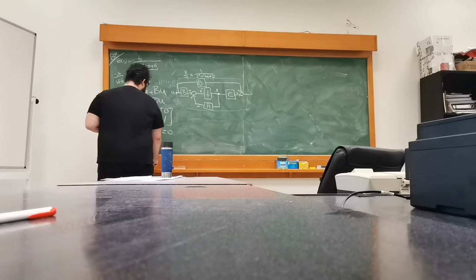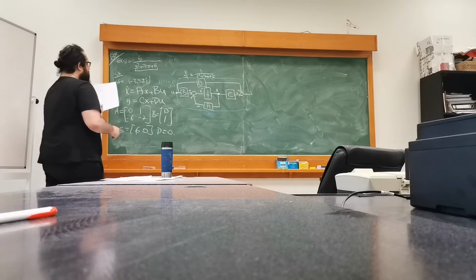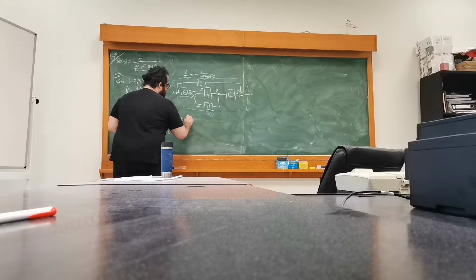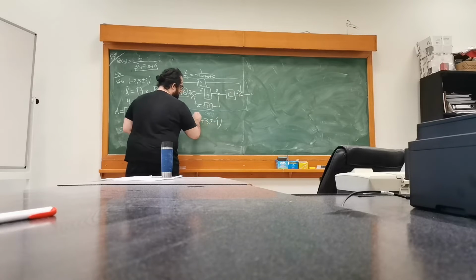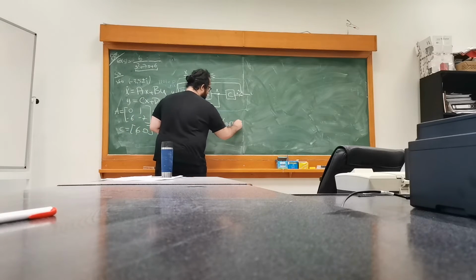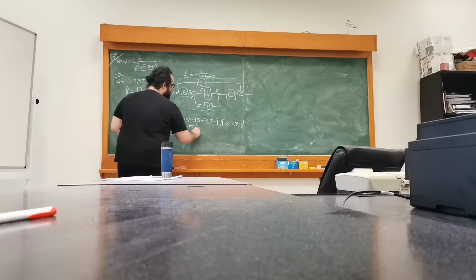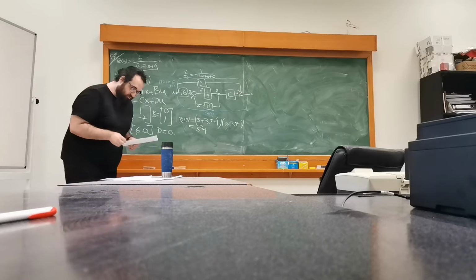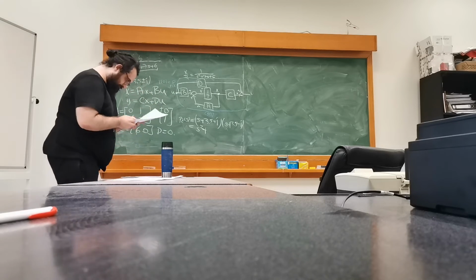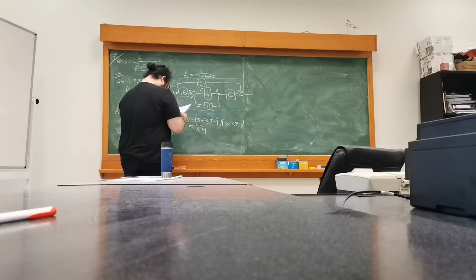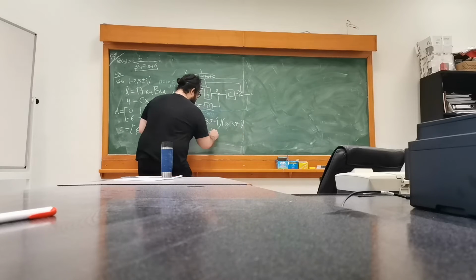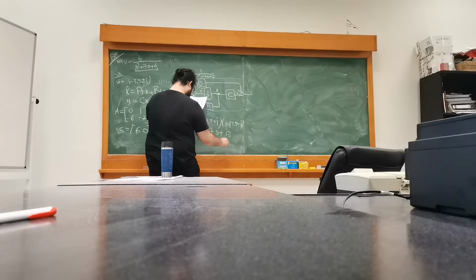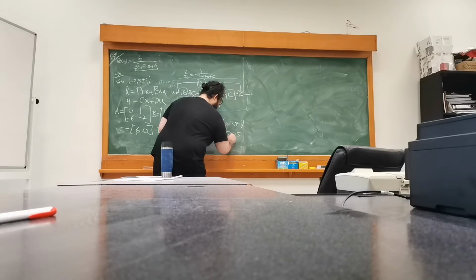So in this case, we have already the poles, and this is basically PD(s), the design polynomial, (s plus 3.5 plus j) times (s plus 3.5 minus j). Or in other words, we have to multiply them, let me look it up. s squared plus 7s plus 13.25. Yeah.